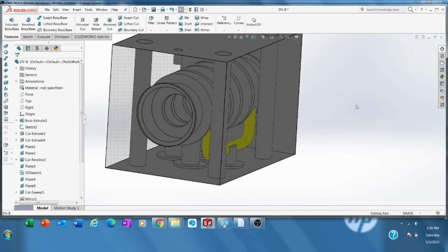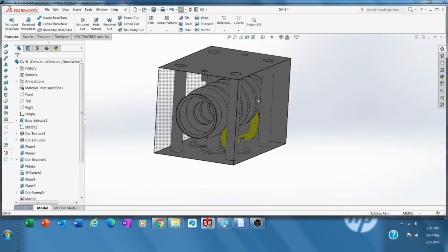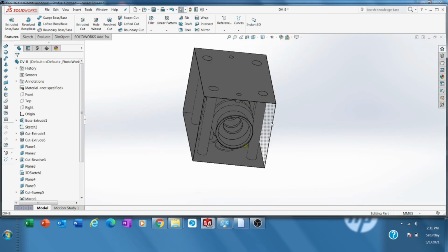So to summarize, what are the key points? The key point is manipulating flow direction by this spool, and the spool has a housing, what we call a manifold house for the directional valve, and how it energizes using a coil, and what kind of coil. Of course, you have 24 DC or 220, depending on your request.